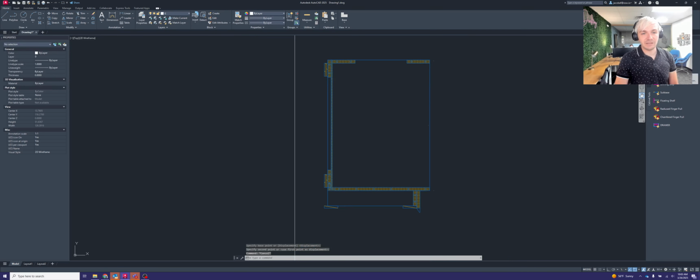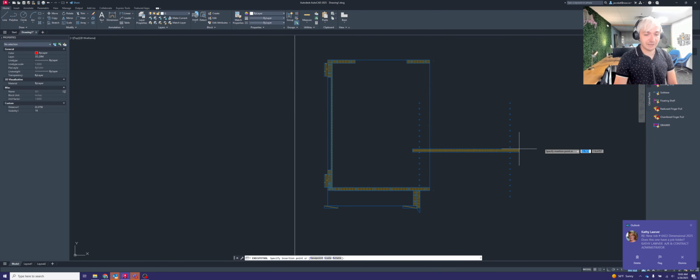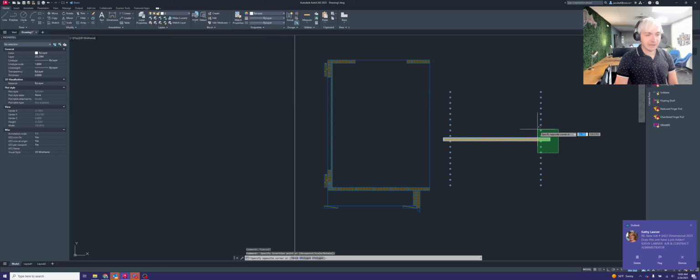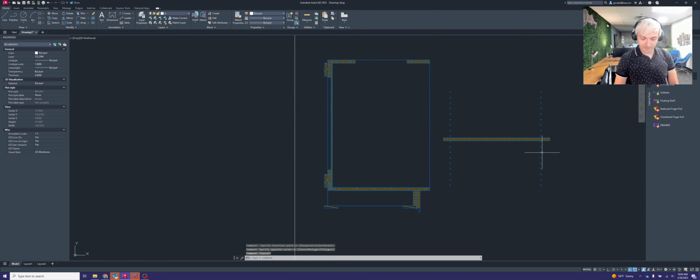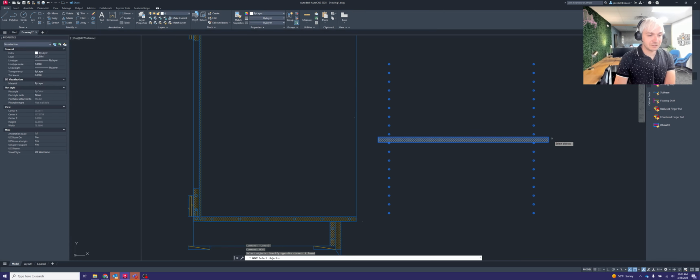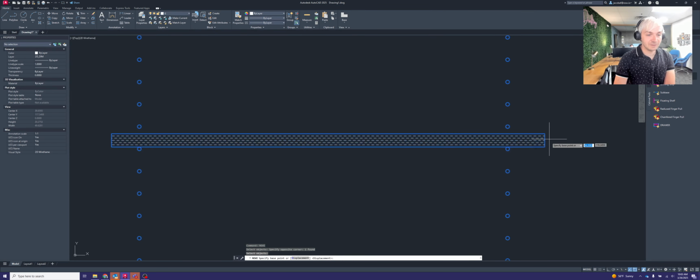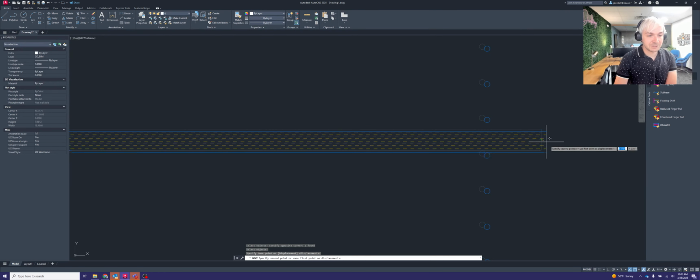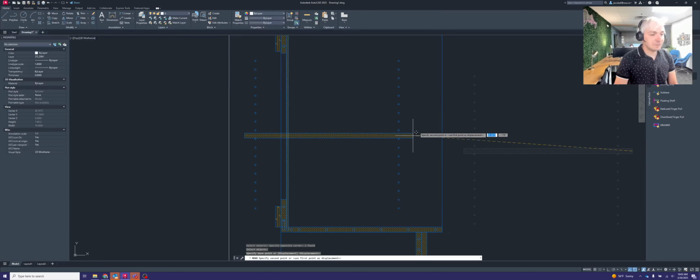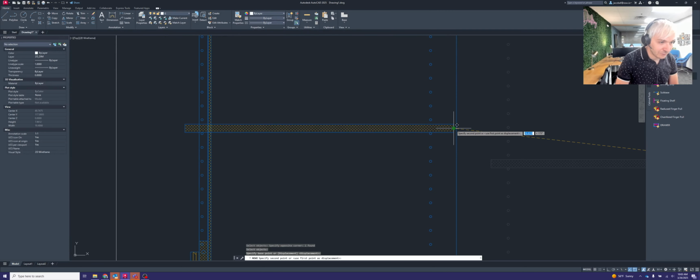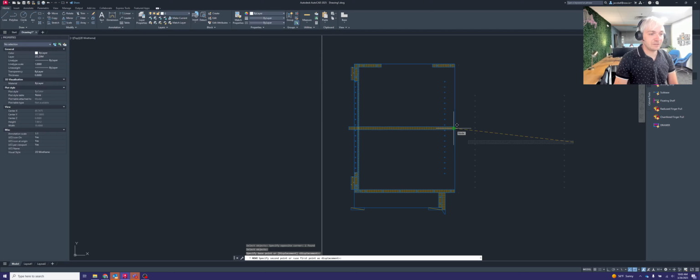So as you get into drawing a cabinet, you have your adjustable shelf. So if the architect is asking for an adjustable shelf within a cabinet, you would bring in the adjustable shelf block. You can use the move command in AutoCAD just by typing that in, hit enter, select this shelf, and then you want to grab the center, so this midpoint right here of that shelf. And it's hard to see, but there's a little white dot right there at the front of the cabinet that is perfectly centered between the top and the bottom of the cabinet,